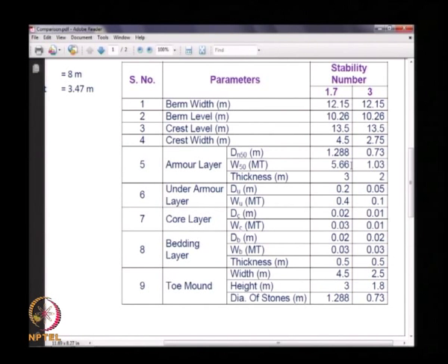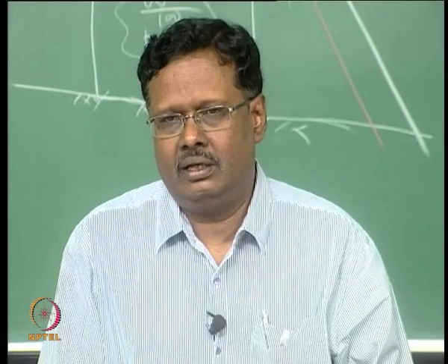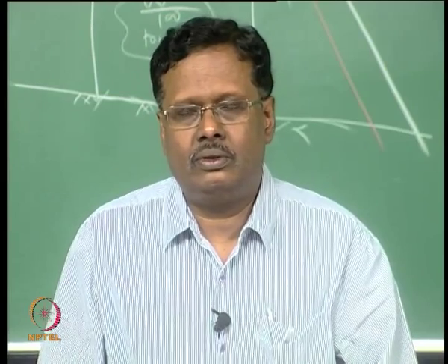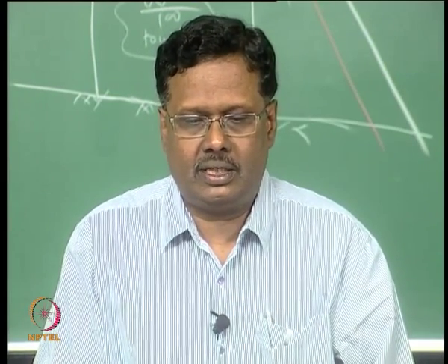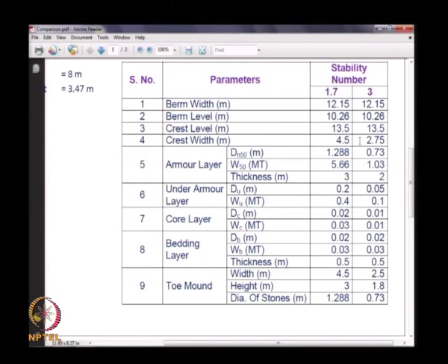So here we have given the comparison. The Hs will not change, the berm width will not change, berm level will not change, crest level will not change, the crest width will be reduced, but for construction purpose we will increase it to 8 meters. That is another important thing when you go for civil engineering or harbor engineering design, there is a formula which gives the width. For construction purpose we have to revise it, for construction as well as for maintenance. Then the armor layer and other thicknesses are given.